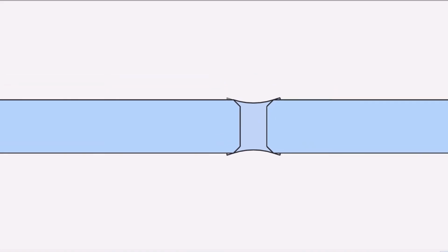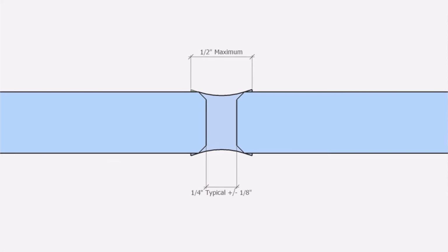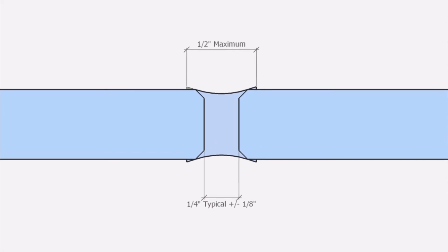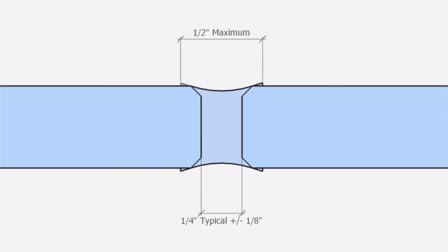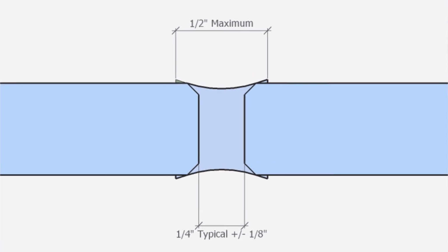We'll provide a detailed explanation of how to construct this type of a joint between adjacent panels. The typical joint size for this is going to be 1/4 inch. That's what we would deduct when we're converting our opening measurements into glass sizes. We're going to allow 1/4 inch for the size of a silicone joint.